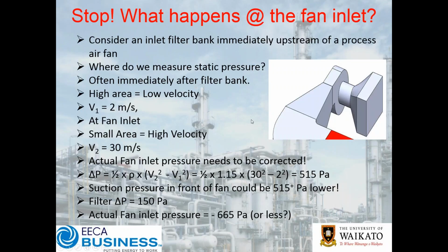Now I've drawn an example here, and this is something to think about. We've talked previously, when we talked about taking measurements in a fan system, about how looking at static pressures is a good guide as to what's going on in the system. Now in most systems, so here's just a CAD schematic, if you will, of a standard centrifugal fan with axial inlet and then coming out the side here, and this is just showing a filter bank to the side.